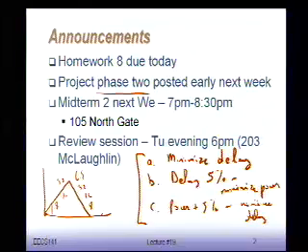There's a lot of things you can do with this structure, as you probably have realized already. The way I connect the adders together, how I massage the critical path, what type of adders to use, because the adder that we have used so far was clearly built for minimizing carry. But if you look at your structure, minimizing carry might not be the only goal. Actually, if you look at the critical path, it might go through some sum paths as well. Maybe you want to use a different adder cell. And as I said, if you want to do dynamic, feel free to do so.